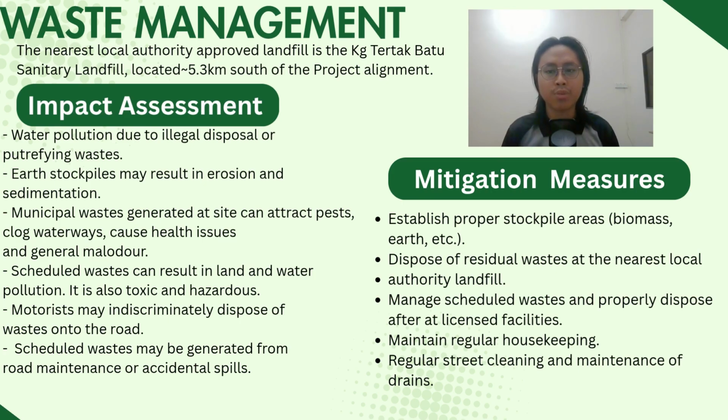So for the mitigation measures to address this issue, we will have to establish proper stockpile areas for biomass, earth, and so on. Dispose of residual wastes at the nearest local authority landfill. Manage scheduled wastes and dispose of them properly at licensed facilities. Maintain regular housekeeping, regular street cleaning and maintenance of drains. This is to prevent any water pollution, erosion or even health issues.